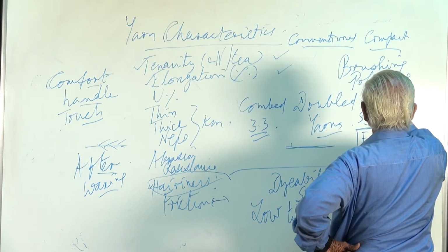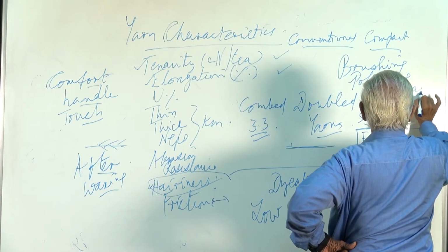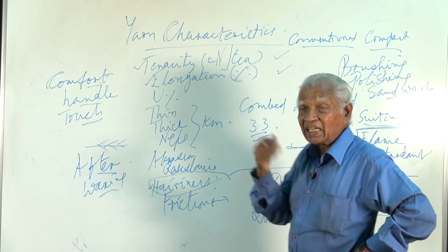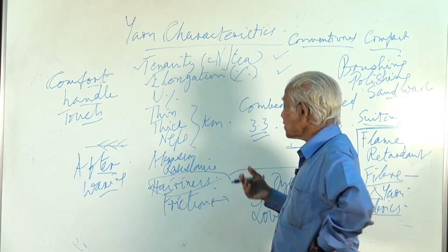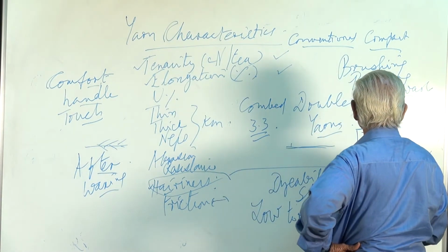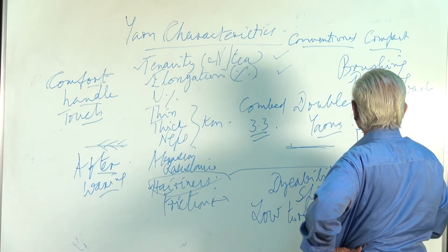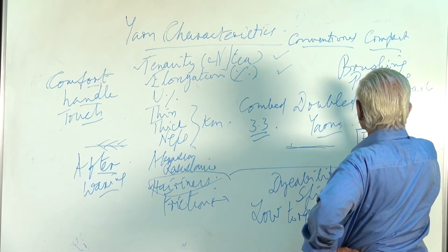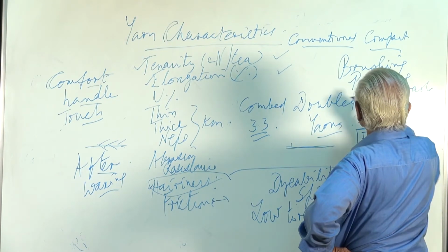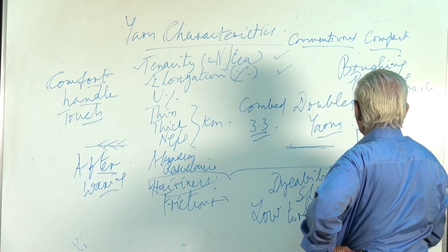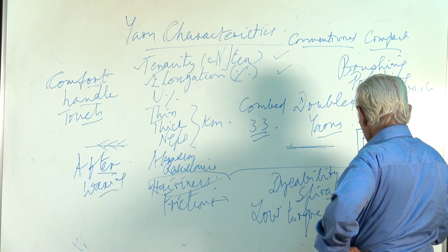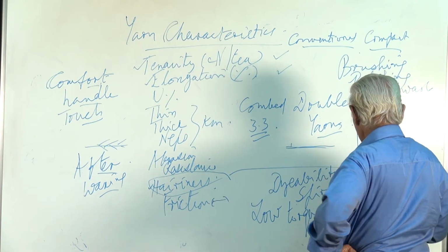This sand wash is very common for knitted fabric to convert that to a flannel-like thing. We talked about the flannel also in one of our lectures. Very soft substance, and it improves the moisture absorption. So this is a mechanical finishing process, and it is advantageous to the fabric in the sense that its absorbency is considerably improved.